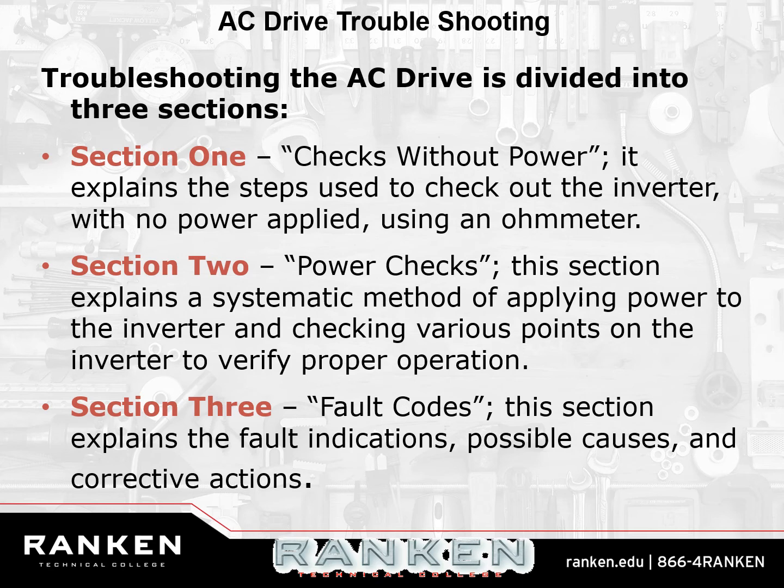The old Square D Altivar drives, the Schneider drives, will tell you what time of day it was, what the ambient temperature was, what the motor temperature was when it tripped. It'll tell you pretty much everything you need to know about the conditions which caused the fault. And it's got a pretty good interface to tell what the codes were and what the faults were. The PowerFlex 40, it just has a code number, F8, fault number 8, and then you have to look it up in the book and see what fault 8 was. So there's a big difference.